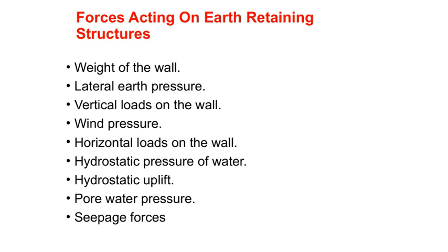Pore water pressure is another critical factor. It's the pressure within the soil pores caused by water infiltration. Elevated pore water pressures can reduce soil's strength and stability, leading to failure if not controlled. Finally, seepage forces arise from water movement through the soil, which can erode materials or create additional destabilizing forces on the structure. Understanding all these forces and how they interact is essential for designing safe and effective retaining structures. Each force plays a role in the overall stability, and managing them properly ensures the longevity and safety of the structure.